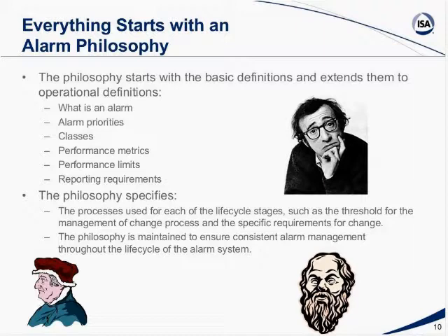But what's really important are the performance metrics. You want to understand what your system's supposed to look like when it's all said and done. If you don't establish metrics up front, you're not going to know whether or not you're going to be successful with your alarm management program. So metrics are absolutely key.